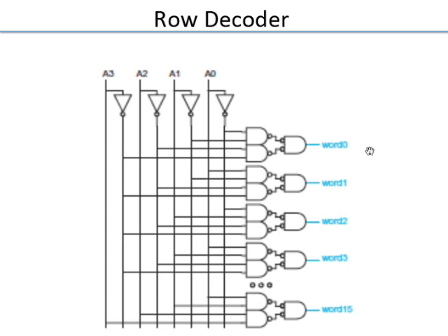All we are saying is, if I want to do a write, then I'll have an additional input out here in this AND gate. Instead of being a 4 input AND gate, I'll have a 5 input AND gate, and then I'll have the write enable going to all of them. Of course, from a design perspective, you can ask, is that a good way? Where should you do that ANDing function? Should you do it here? Should you do it somewhere else?